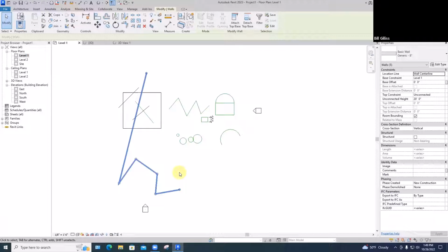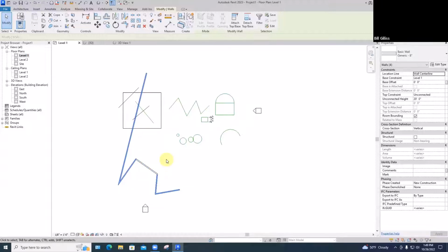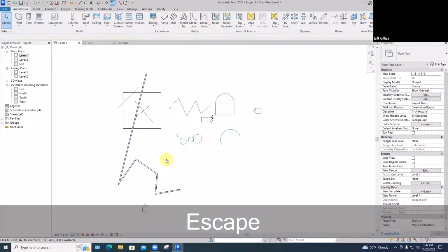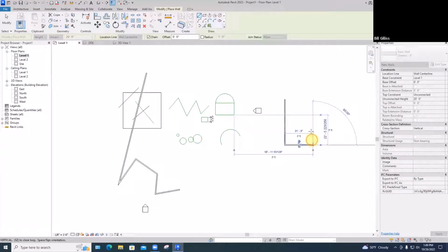Connected end to end doesn't count for things that are sort of T intersections. If I realize I want all of those except this, that one right there, once I've got things selected, I can use shift click to deselect just that one guy. So that's handy if you've windowed a bunch except for 2 trees or something, you could then shift click to get rid of them. And lastly, let's draw some more walls. And this comes up a great deal.